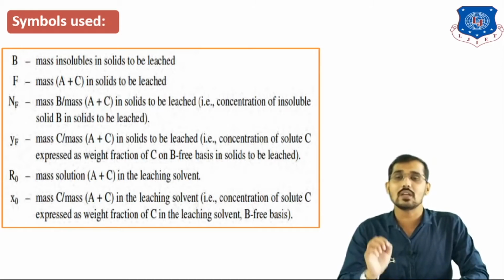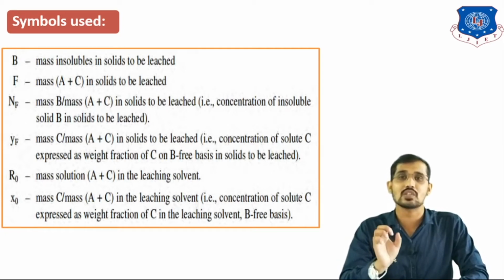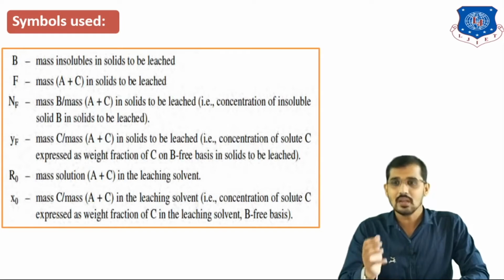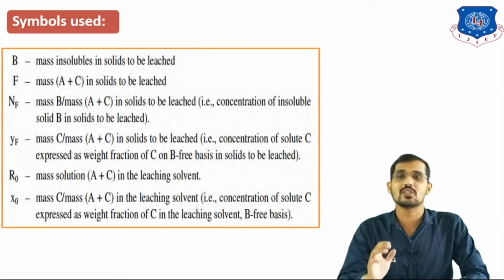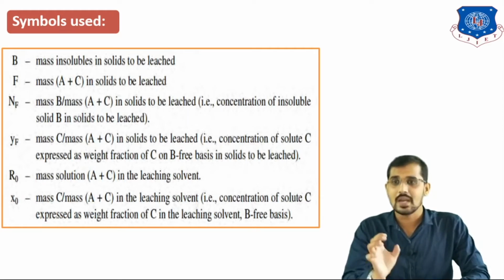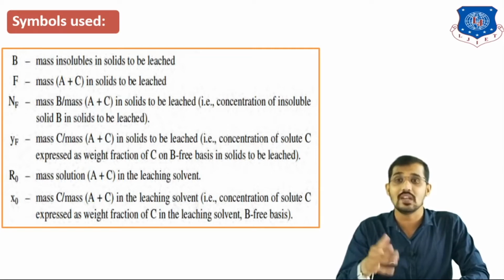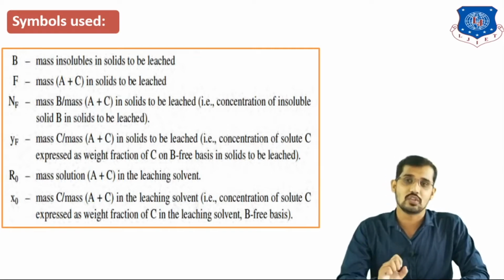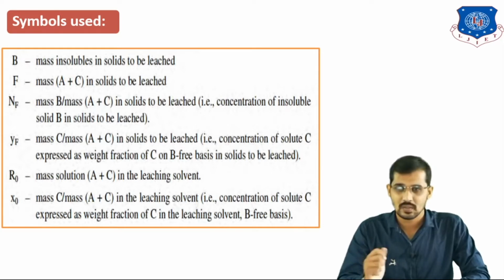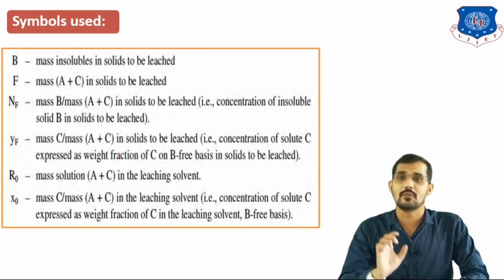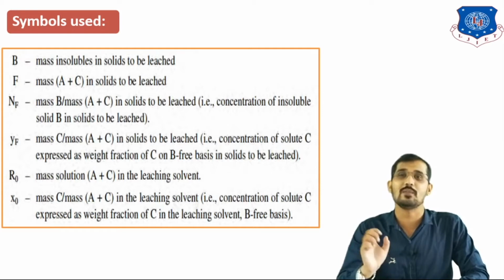This is nothing but the mass fraction of the solute. You can see here mass of C, that is C is nothing but your solute to be leached, divided by mass of A plus C in the solid to be leached. The solid to be leached is nothing but your feed stream, and YF is nothing but the mass fraction of the solute in the solid to be leached. That is also on an insoluble-free basis, or I can say component B free basis.